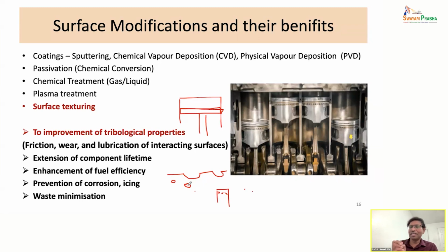So that automation, that means making the fuel into small particles when you are injecting into the combustion chamber, is very, very important. And that is improved with the help of micro machining technologies and even with lasers. So we can make the holes very, very small. So that improves the combustion.